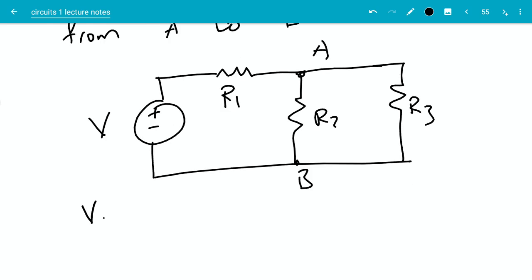So the potential difference between A and B, VA minus VB, is, again, let me not write the definition again, basically the amount of work required to move a unit charge from B to A. Now usually it will be convenient for us to talk about potentials at different points on the circuit as opposed to potential differences. So in order to do that, we pick any point on the circuit and call that our reference point.